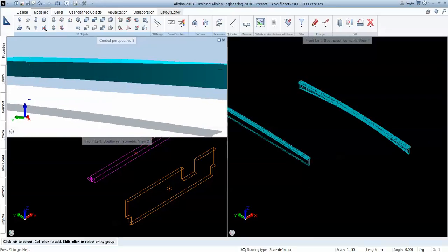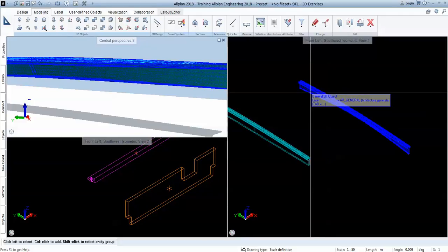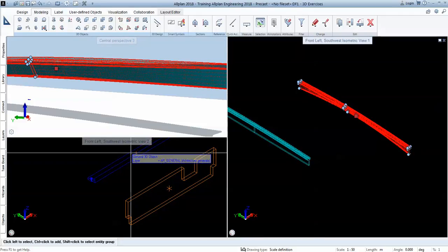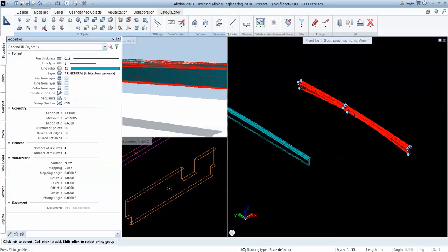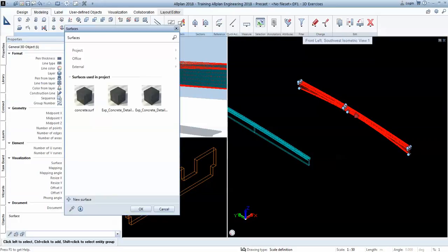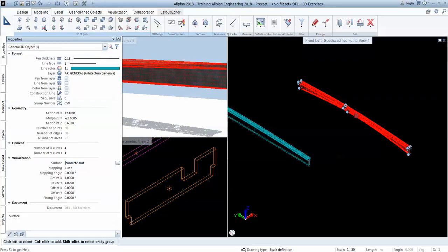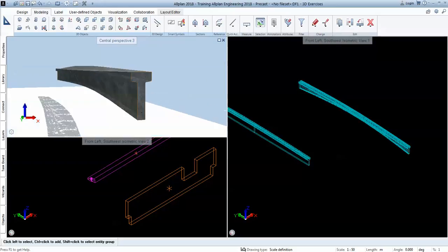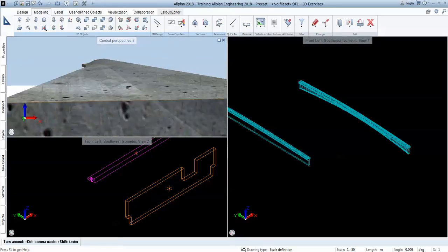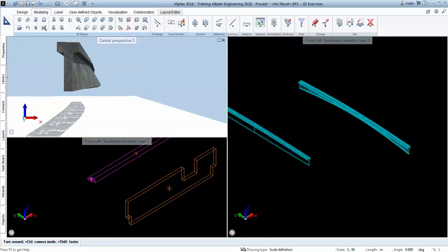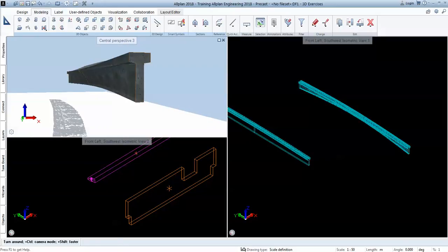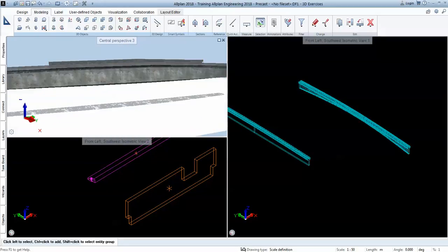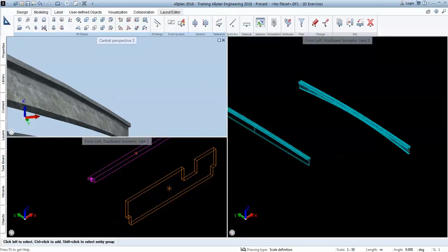So I did this modification just to illustrate how this loft works. All the loft functions work with profiles, which are not made of 3D surfaces, but of 3D lines, positioned so that it is plausible from a geometric point of view to obtain some intersection. So now you see the intersection. So this is how I can get from profile number 1 to profile number 2 and back to profile number 1 in between.